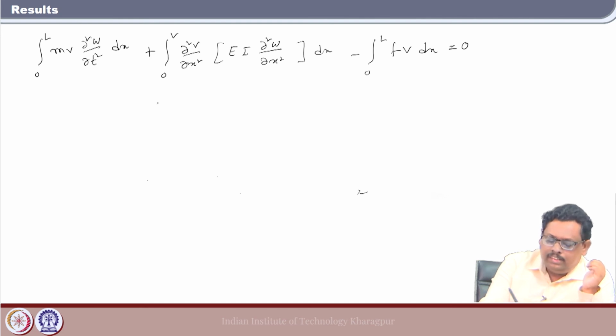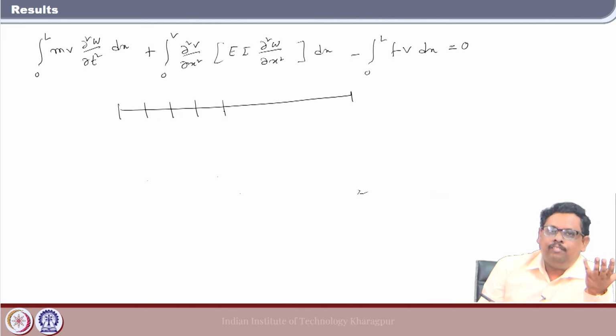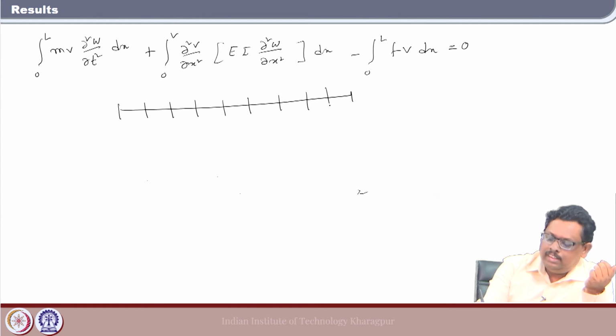Now, what I do is, if we assume this is a beam element, so similar to the panel method, you know the panel method, so you do not have difficulty understanding this. So, assume these are the elements, this could be element number 1, this could be element number 2, assume that there is an element number E. Now, if you take this element E, then I can allow 2 degrees of freedom at each node.